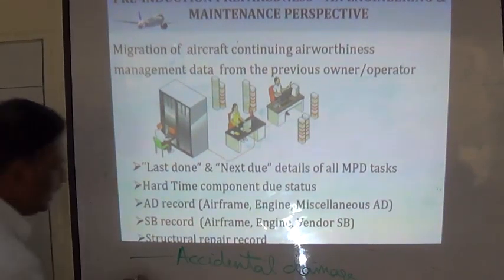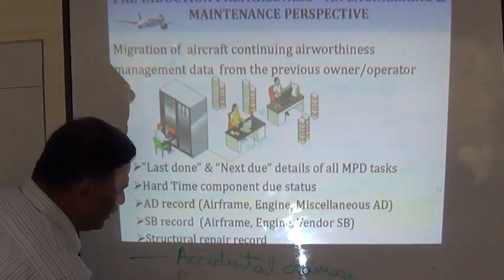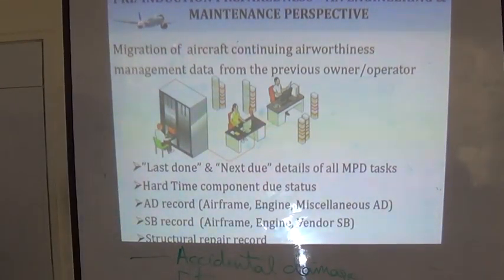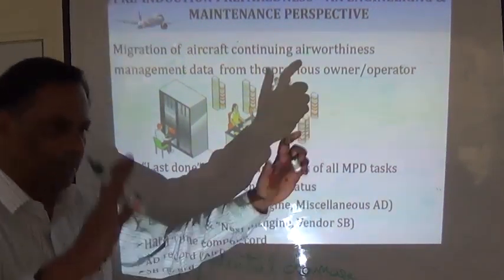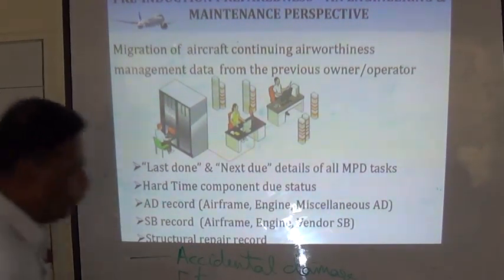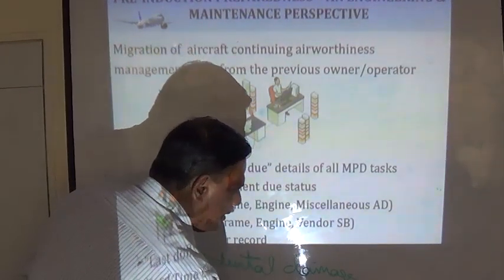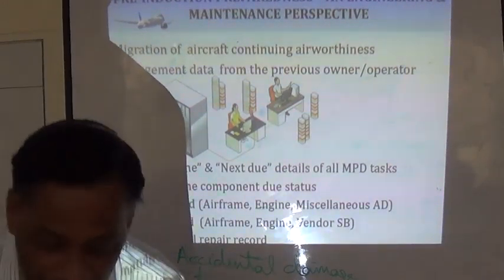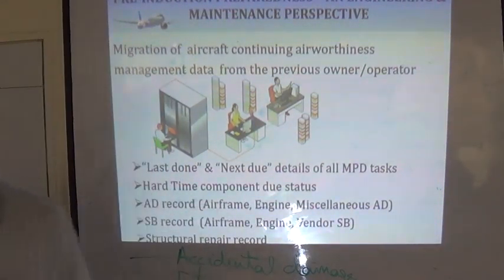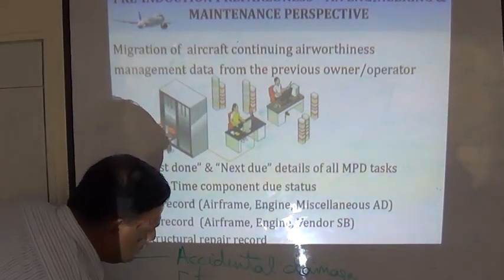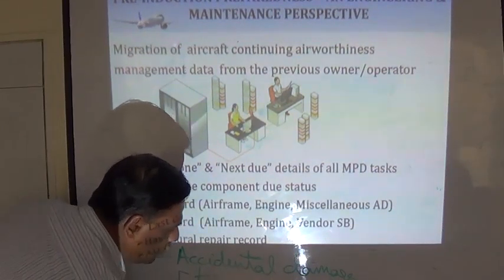Next is called fatigue damage. Because for every landing and takeoff, the aircraft airframe is going through fatigue stresses. This fatigue will result in cracks developing in the body of the aircraft. So fatigue damage will start originating some cracks. And if these cracks are in places where a maintenance person cannot see, they remain unattended. Third is called environmental damage, which is mostly related to corrosion.